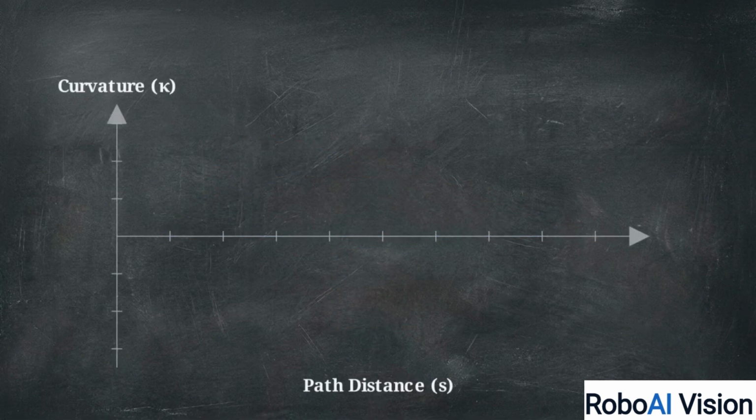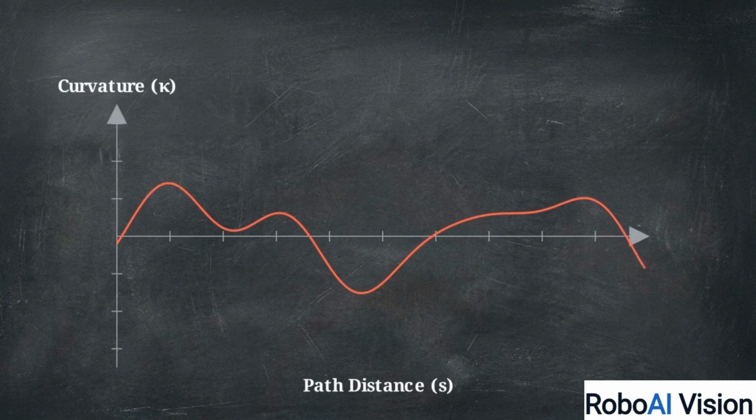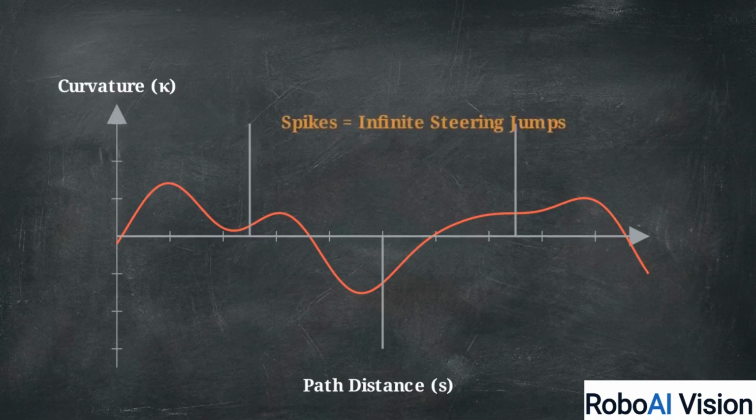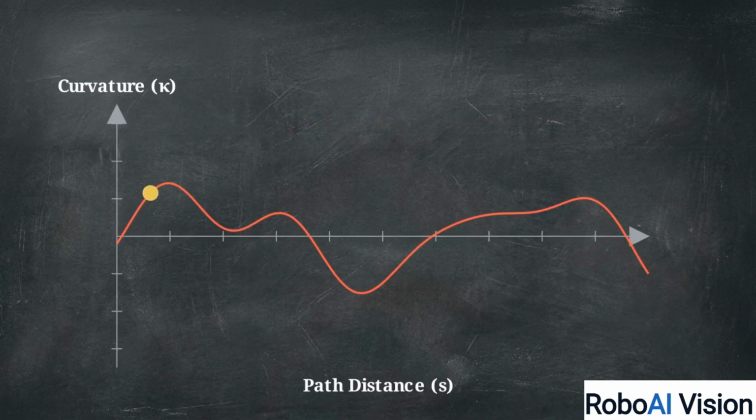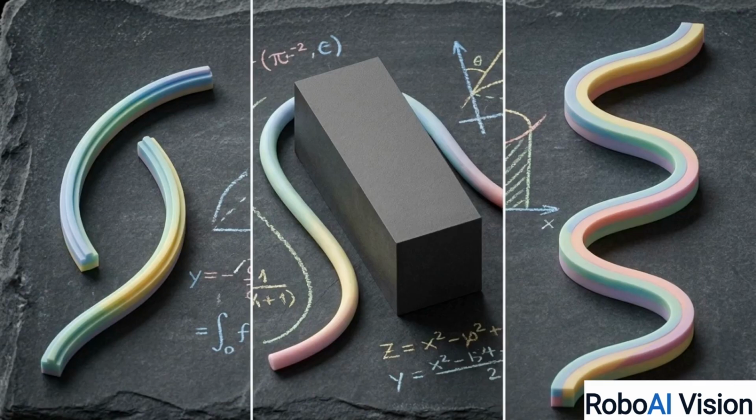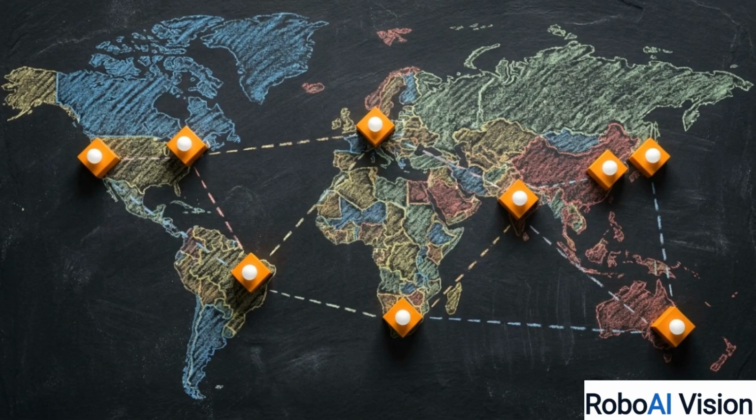The third and most important property for physical mechanics is C2 continuity. It dictates that the path is unbroken, and its curvature, represented as kappa, is entirely continuous. There are no vertical spikes, providing the robot with smooth, progressive steering commands instead of impossible jumps. These three theoretical pillars, local adjustments, guaranteed obstacle clearance, and unbroken steering curves, create a highly robust framework for robotic motion control.